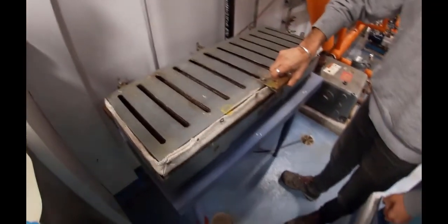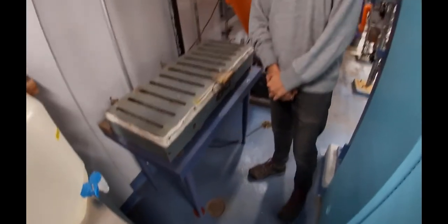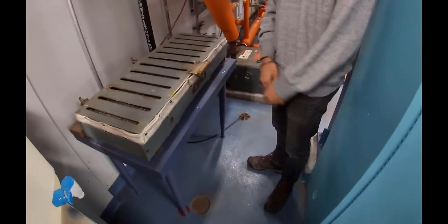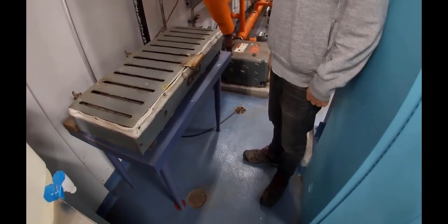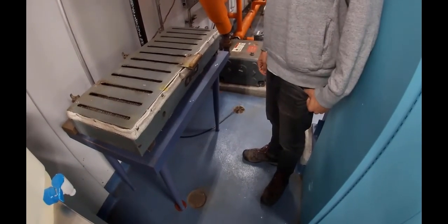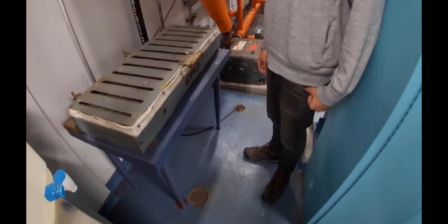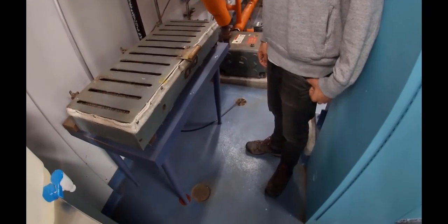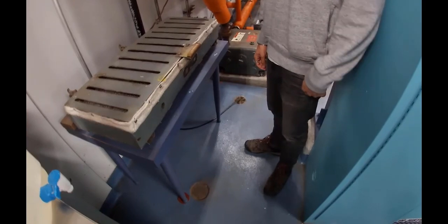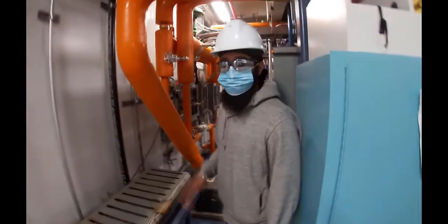And now we're going to dry that out. So basically, we'll dry it until the weight actually stops changing, and then we can calculate the consistency from the weight of the pad minus the weight of the filter paper, divided by the weight of the slurry. Okay, you've taken the beaker out of that, and multiply by 100. There's your percent consistency. Thank you, Nick.